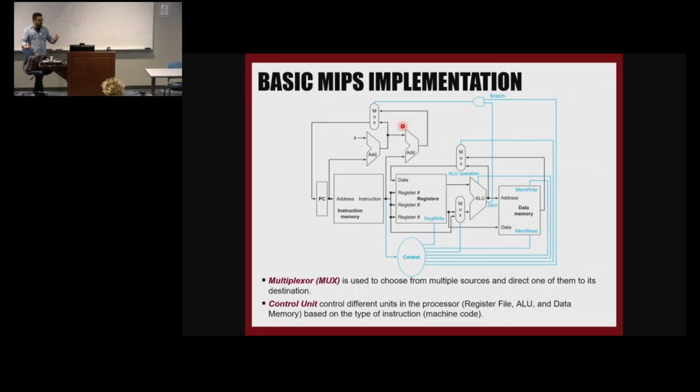This 0 flag, this is again one of those other things. Every time the ALU does a computation and returns a 0, even if I want to add two numbers, if the result is 0, the flag is going to be set to 1. The flag doesn't know that I'm doing a branch or add or whatever. It doesn't care why I'm getting a 0 at the output of the ALU. It just sets the flag to 1. We are responsible for creating a mechanism to make sure that the 0 is created for a branch or it's not created for a branch.